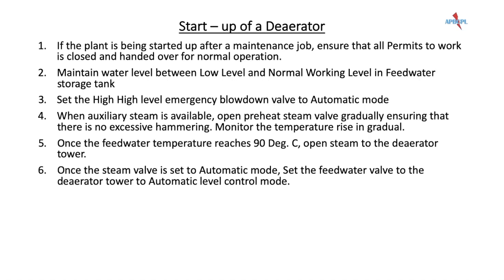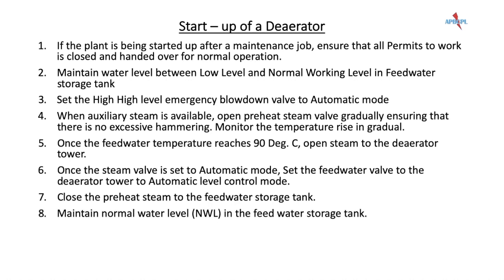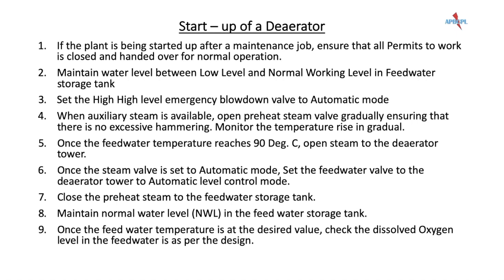Once the steam valve is set to automatic mode, set the feed water valve to the Deaerator tower to automatic level control mode. Always open the steam valve first before opening the feed water valve. Now close the preheat steam to the feed water storage tank. Maintain normal water level, NWL, in the feed water storage tank as the Deaerator is ready for its normal operation. Once the feed water temperature is at the desired value, check the dissolved oxygen level in the feed water as per the design.